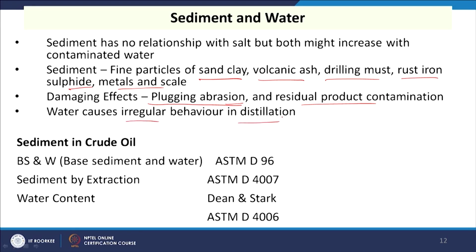in the distillation. For the measurement of this there are a number of methods: base sediment and water measurement, ASTM D96, sediment by extraction ASTM D4007, and water content by the DIN or ASTM D4006 method. Now, we will be discussing some properties of the refined products, that is your octane number.